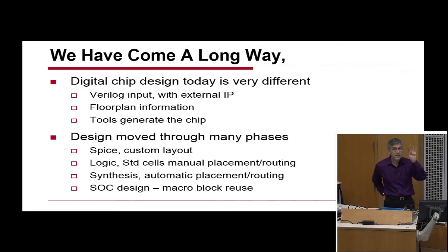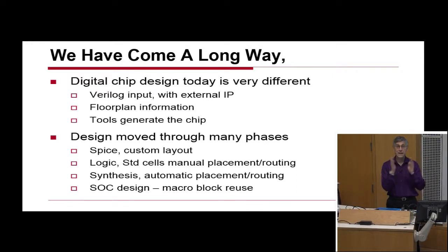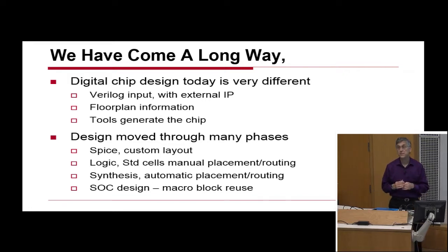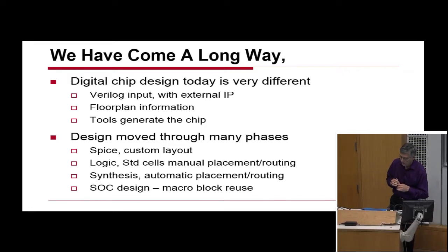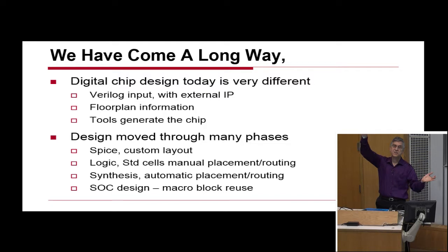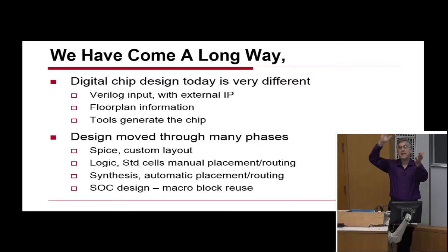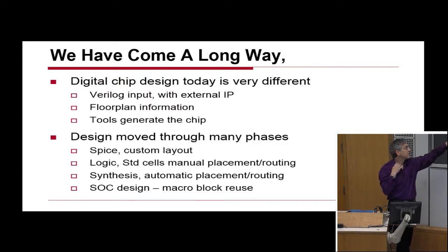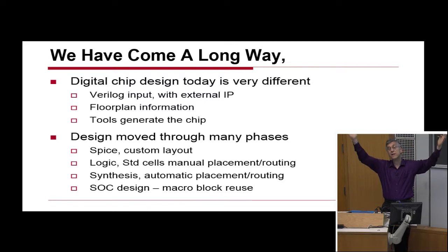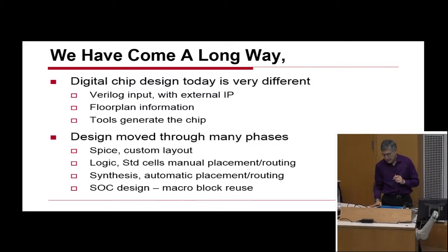We do some floor planning at the top level, and we basically generate the chip. And if you think about that process from the early '80s, late '70s to today, we moved through many phases. We started with SPICE and custom layout. We did the logic and standard cells. Then we did synthesis and automatic placement and routing. And then we went to SoC design and used macro blocks to increase the complexity of the design so that we could deal with it.